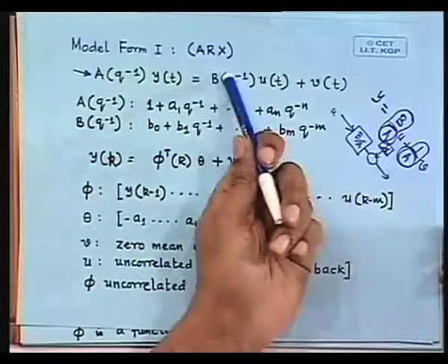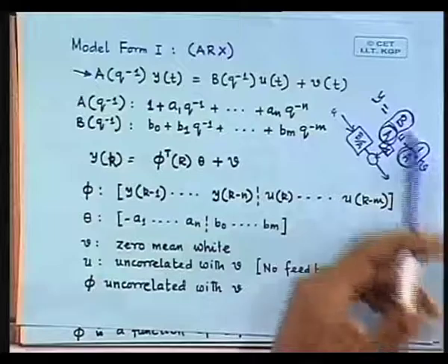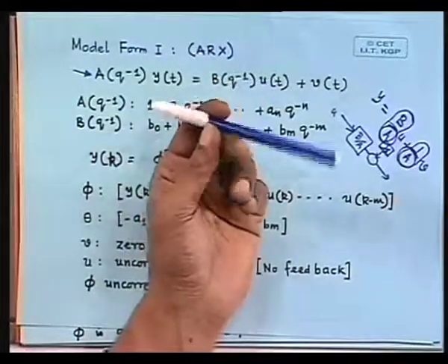If you use this model structure, you must have some basis of thinking that any noise that may be coming is also coming through the same set of poles, which means that it must be some noise structure. Now what is that signal which gets filtered through the a polynomial? It is the state, because what is the state to input transfer function? That has zI minus A inverse.